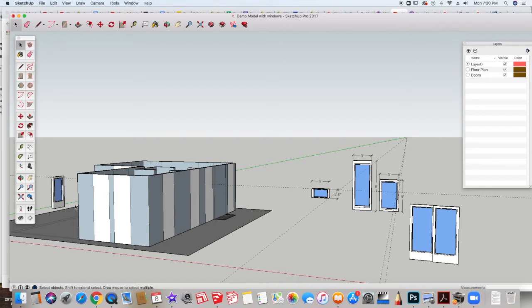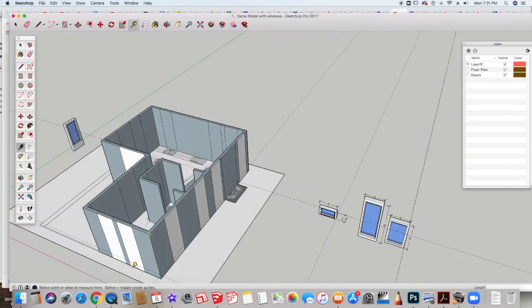So the first thing we're going to do with our model before we put our windows in is we're going to make the holes for the window, just like we did in the interior design project. To start, because we're building on a foot-high pad or with a foot-high foundation, I'm going to pull a guideline up that goes 1 foot. And I'm going to click enter. And this is going to give me the guide on where my bottom sill is going to be, because later I'm going to go in and I'm going to pull the floor up.